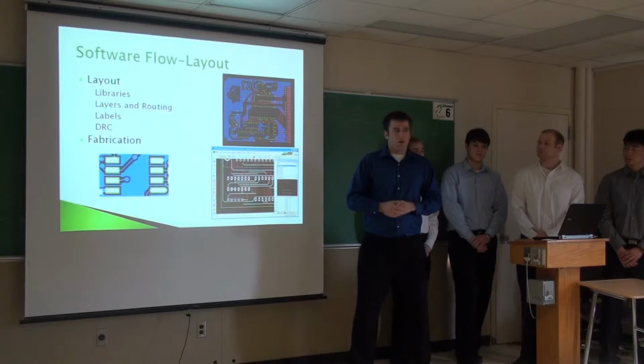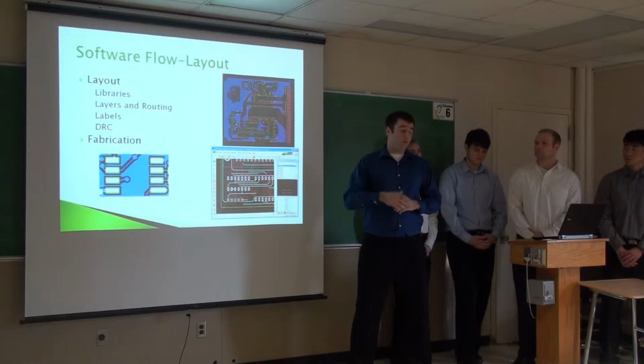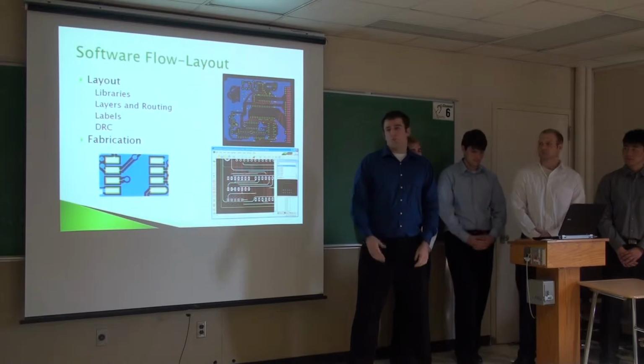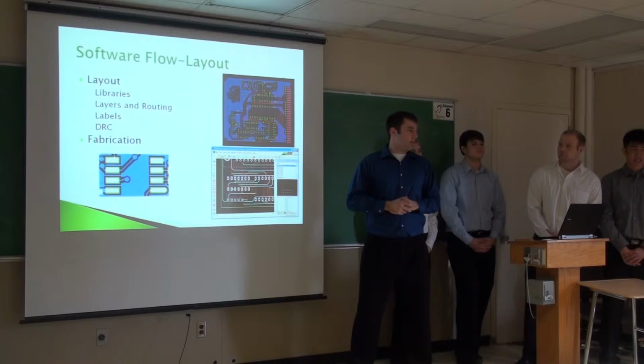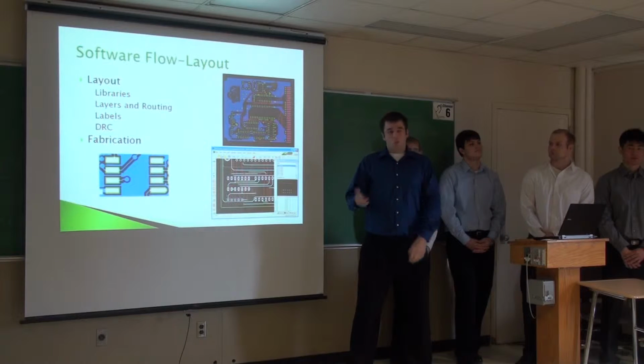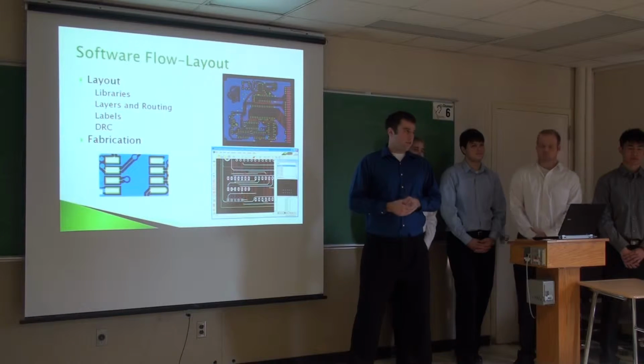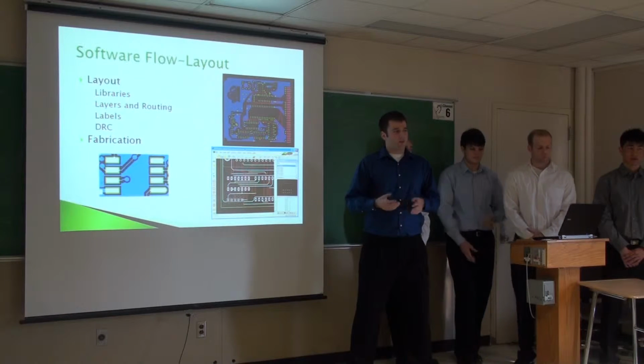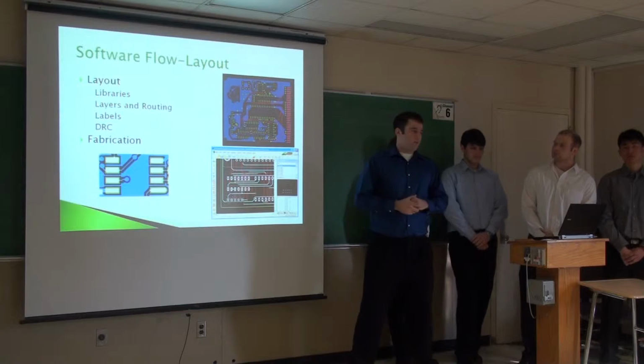There are two ways to do this. Some software packages are actually linked directly to a website, and if that's the case, it's as simple as clicking an Order Now button on the layout software, and you can generally go through a wizard, and it will send it off, and it'll get fabricated. Some are more open, and you can actually generate Gerber files. These can be sent to multiple vendors. You can choose your vendor, maybe shop around a little bit, and then they will fabricate it for you.